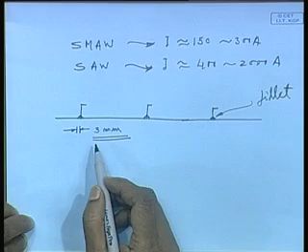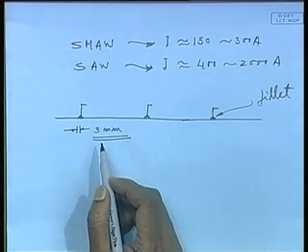What in practice many a times happens, as I have already told you, is that it is easier to over deposit material. Easier means what? Means you set the current at a higher level, choose a higher diameter electrode and go on depositing, go on welding. So, it will be rather easier to deposit 5 millimeter fillet than 3 millimeter, because for 3 millimeter you have to be more precise. That is why one will have to look for pulse mode power supply, wherein you can further control the deposition pattern, right.